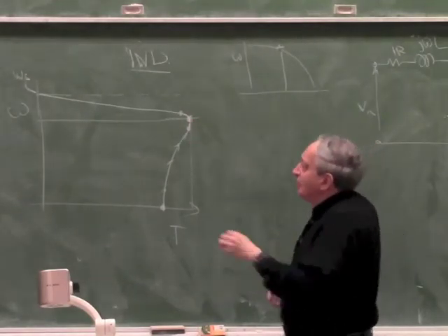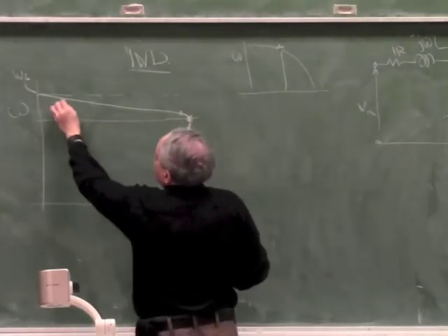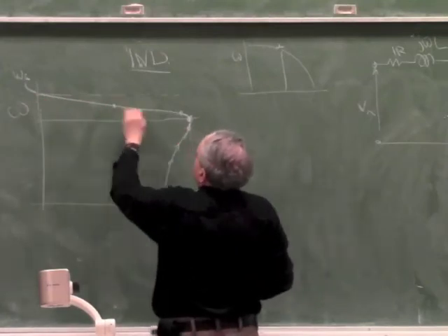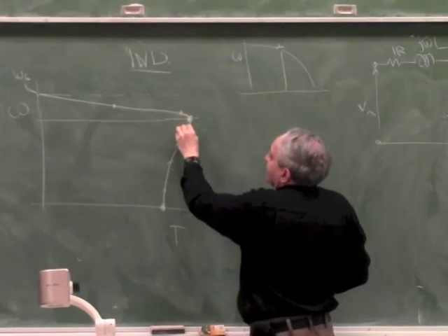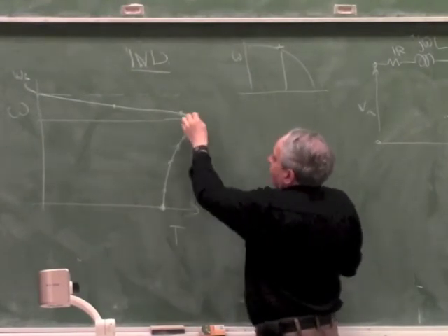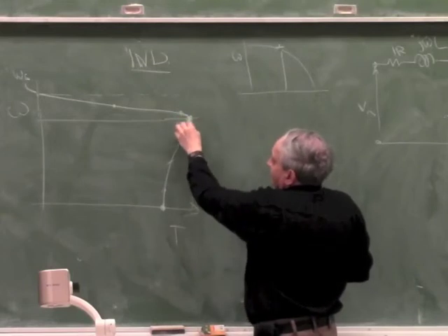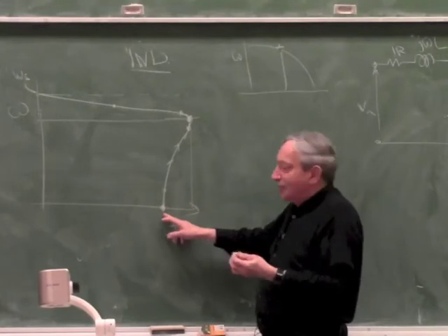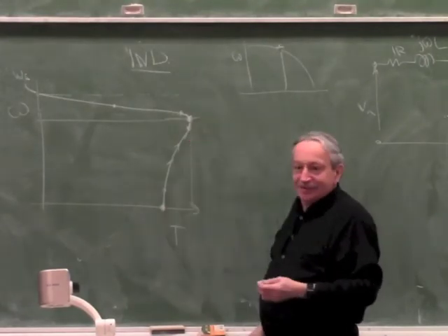If you take away the load, it will just run up here to a lower slip. Okay? So this is like a low load, and this is full load, and if you go too high above full load, it's not going to work. Because if you try to get the torque higher than this point, it's going to stall. But as soon as you remove the load, it'll climb back up. Yes?